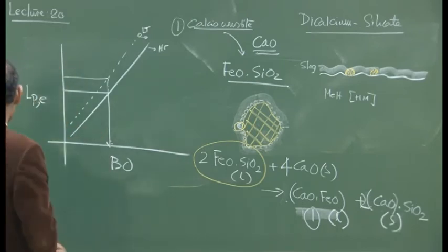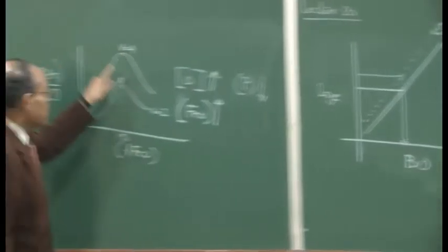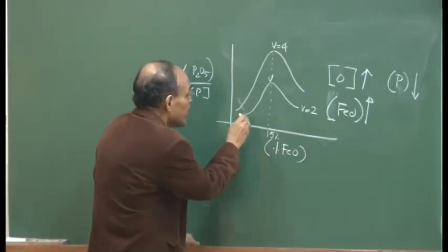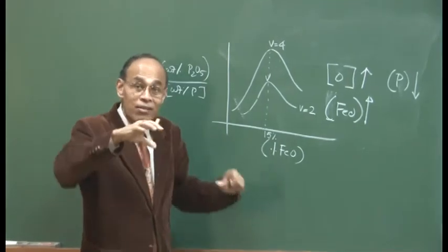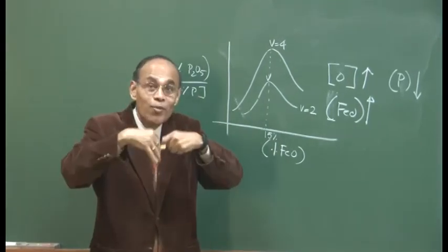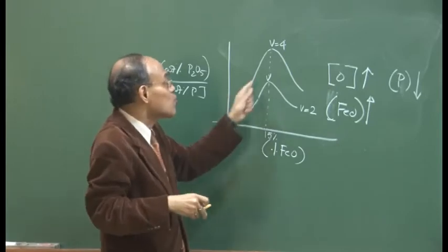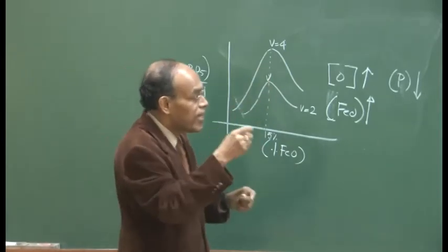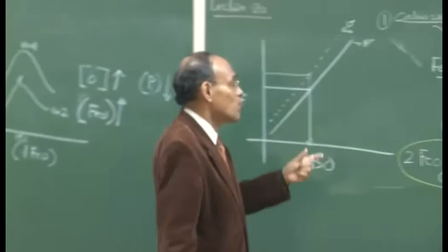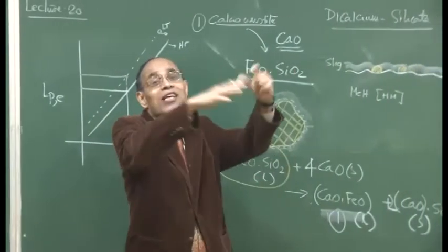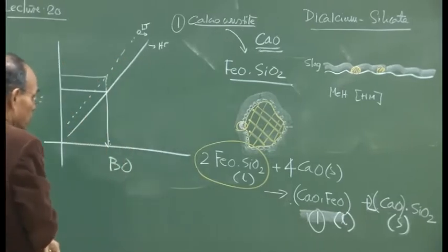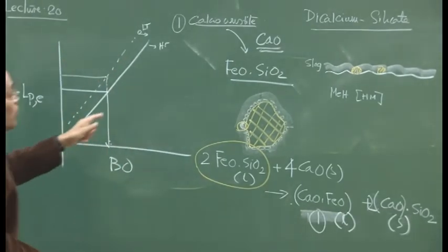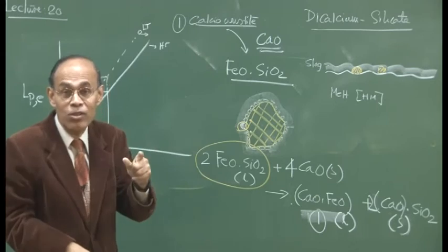When you have 5%, 10%, you do not see this phenomenon, because the progressive dissolution of lime is still not that impeded, but once you cross 15%, the dissolution of lime is really going to be hindered, because it is not exposed to the surrounding slag into which the lime can go. And you can see that we were targeting a basicity of about 4.